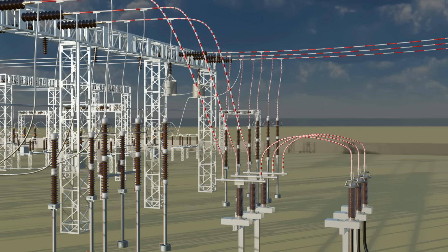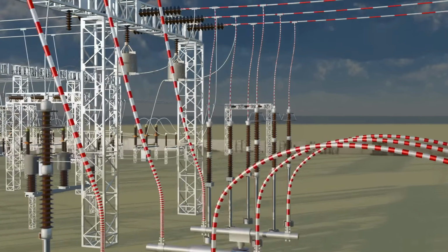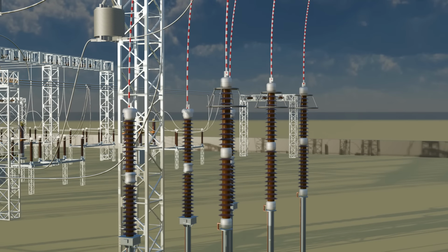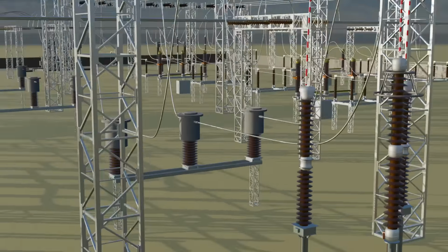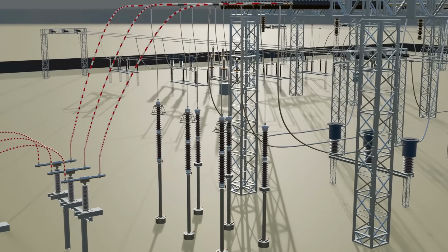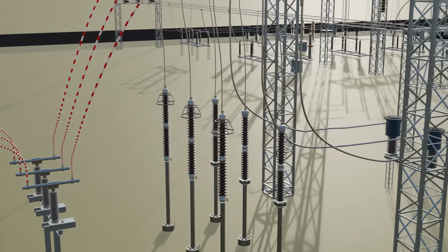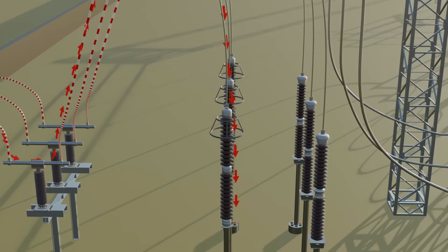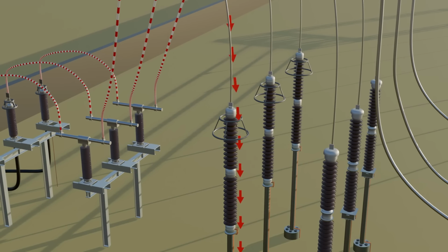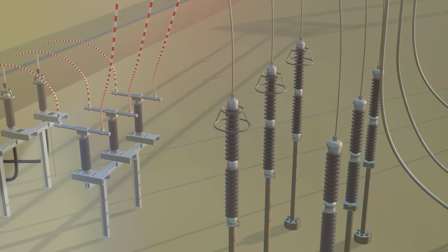In an overhead transmission line, the lightning arrester diverts lightning surges safely to Earth. In cable transmission, there is no direct lightning strike on the cable, but the LA is still used to earth any surges that enter the system. The equipment ahead mostly remains the same.